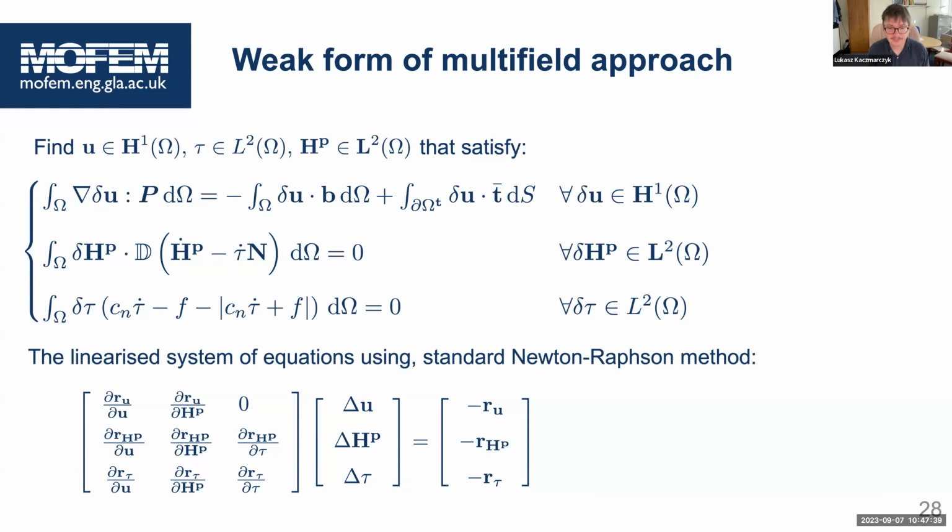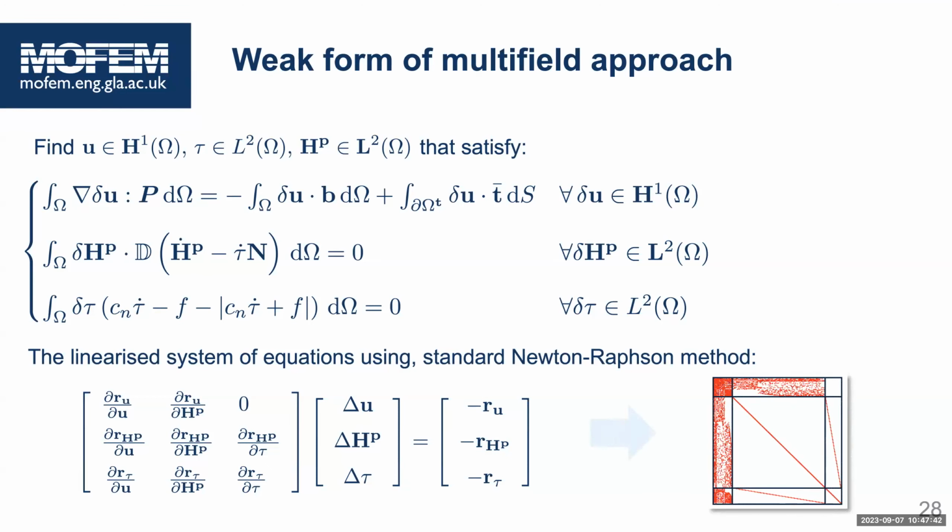Okay. So basically, we'll have per element separate degrees of freedom. Yeah. So when you choose, for example, h to be approximated as a constant per element, you will have 6 degrees of freedom. But when you choose a linear function in 3D, there will be 4 times 6. 4 times 6 is how much? It's 24. So you see the number of degrees of freedom will very quickly grow.